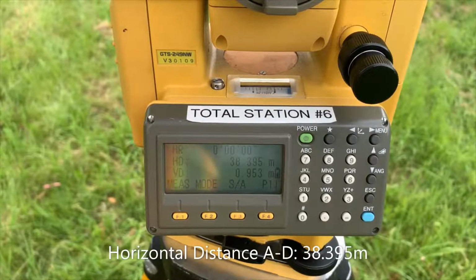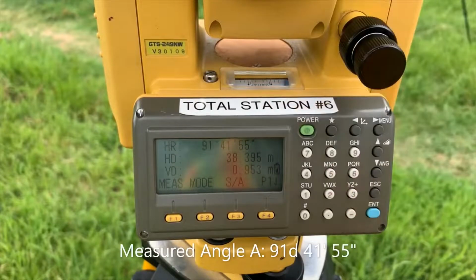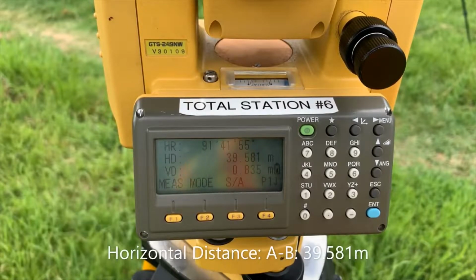That is our horizontal distance from A to D. So now we've rotated our total station and sighted on a prism over B6. We can see our horizontal rotation is 91 degrees, 41 minutes, and 55 seconds. And we'll take a distance measurement, and our horizontal distance is 39.581 meters. So that's from A to B.